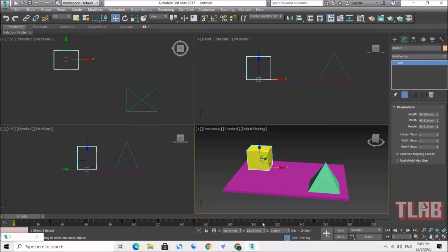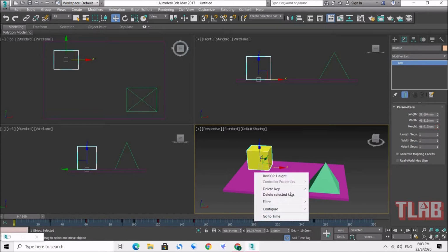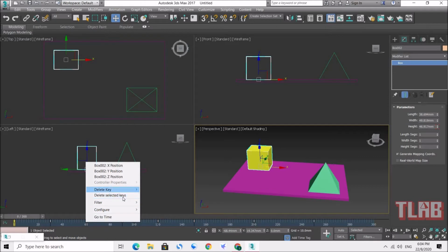And then another one, if you don't want the record, so you can select. Okay, just click, right click, delete selected key if you want. You can remove the point and then cancel the animation for this point. Okay, or maybe you can highlight the old one and then right click, delete. Okay, then after that totally don't have any record for the animation.